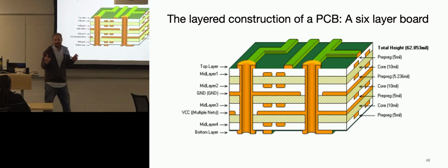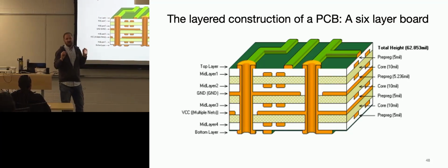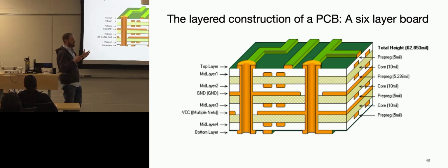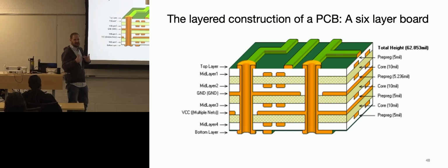FR4 is an epoxy. FR4 stands for Fire Retardant Class 4, which means that it's unlikely your PCBs are going to burn a lot. You can burn them a little bit easily, but they will not burn on their own. If you ever need to cut FR4, it's fiberglass, it's toxic, it gets in your lungs, it'll cause cancer eventually, so don't do it a lot. Not immediate cancer, it's just eventual cancer.